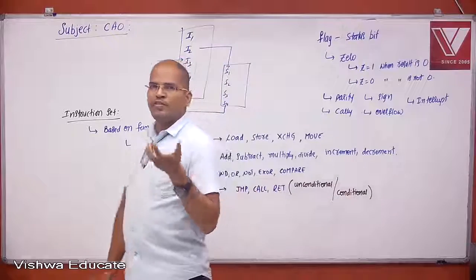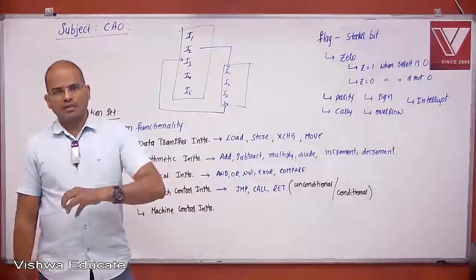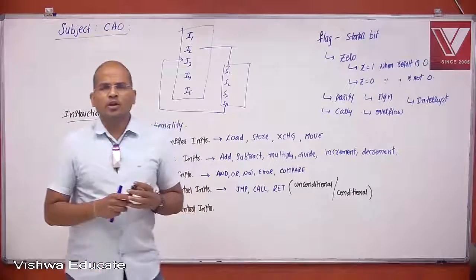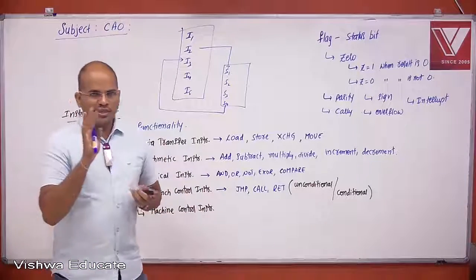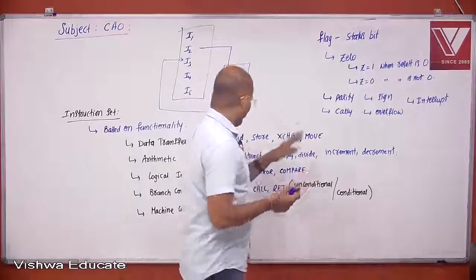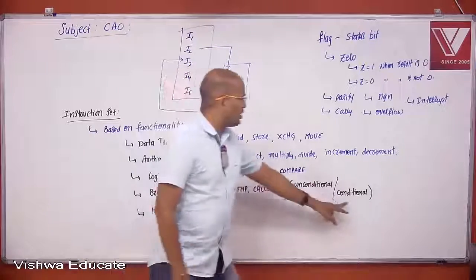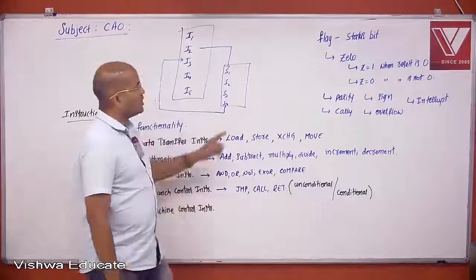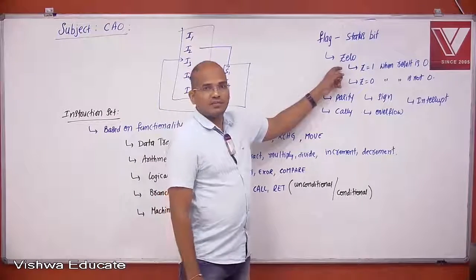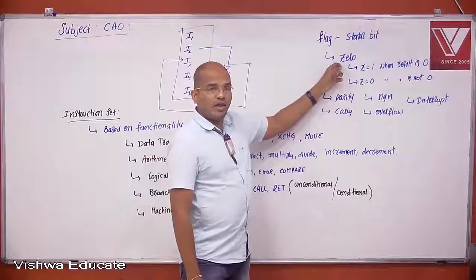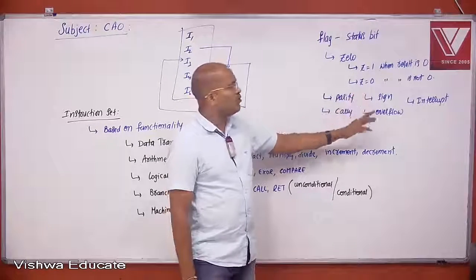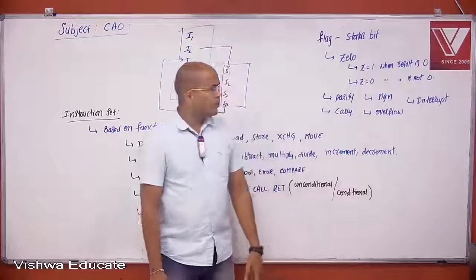So jump if even parity, jump if odd parity. You can frame things according to the convenience, according to the program logic. So please keep in your brain that we perform conditional branching based on the flag status: based on zero flag, based on parity, based on carry, based on sign, based on overflow, based on interrupt. And I hope you all know the word interrupt.